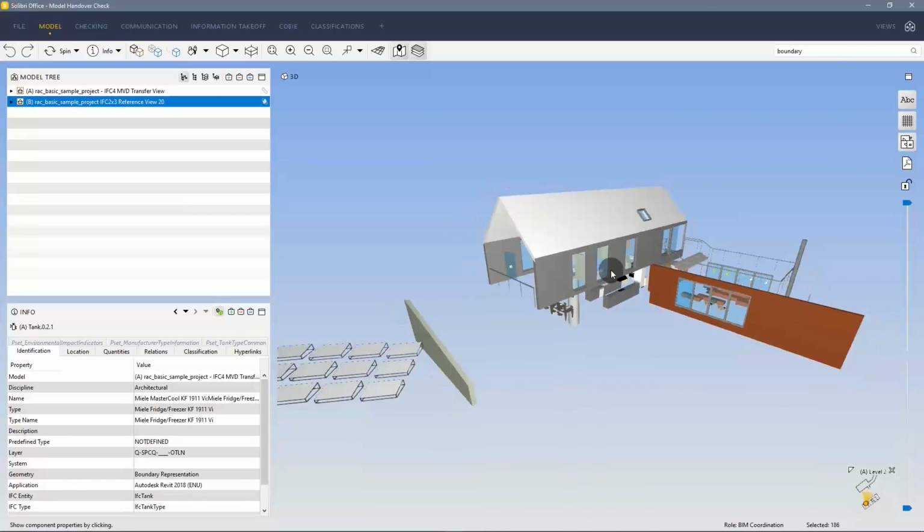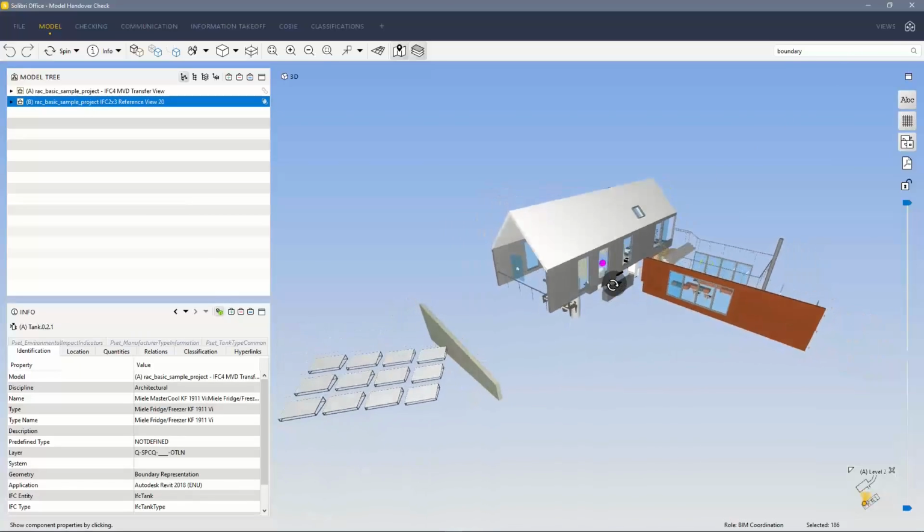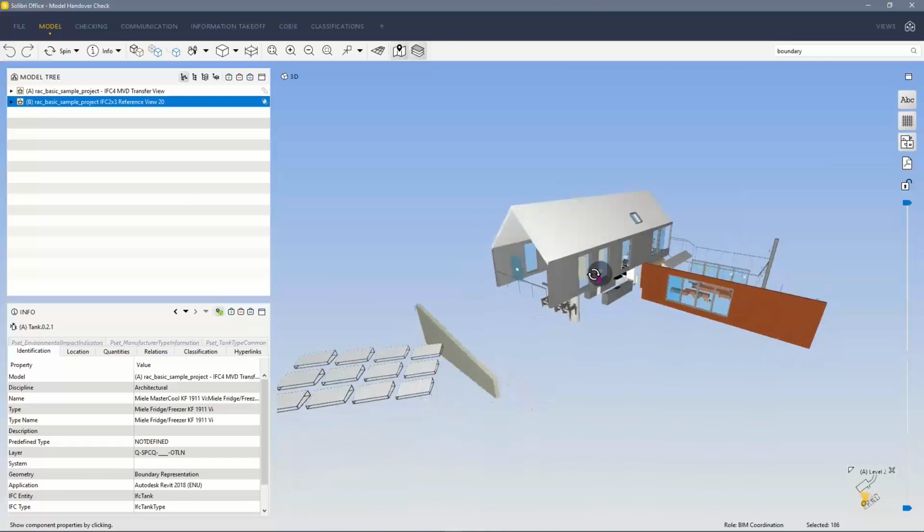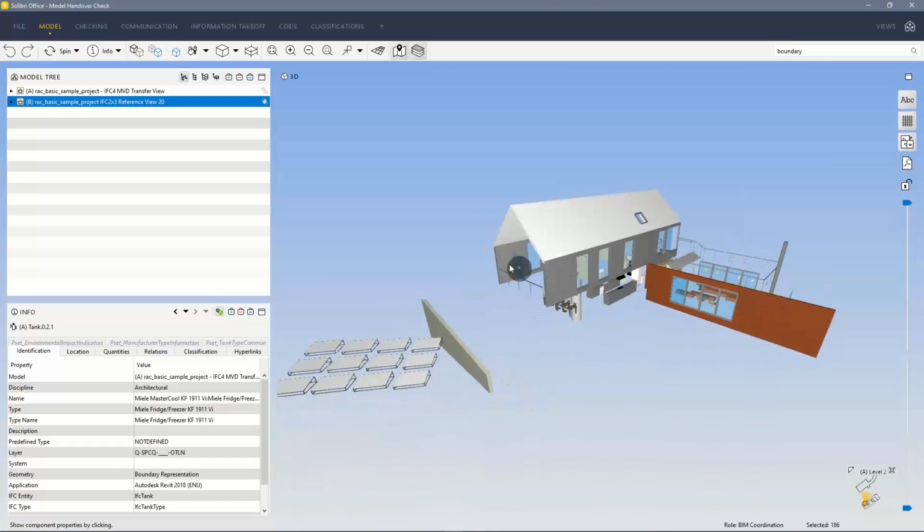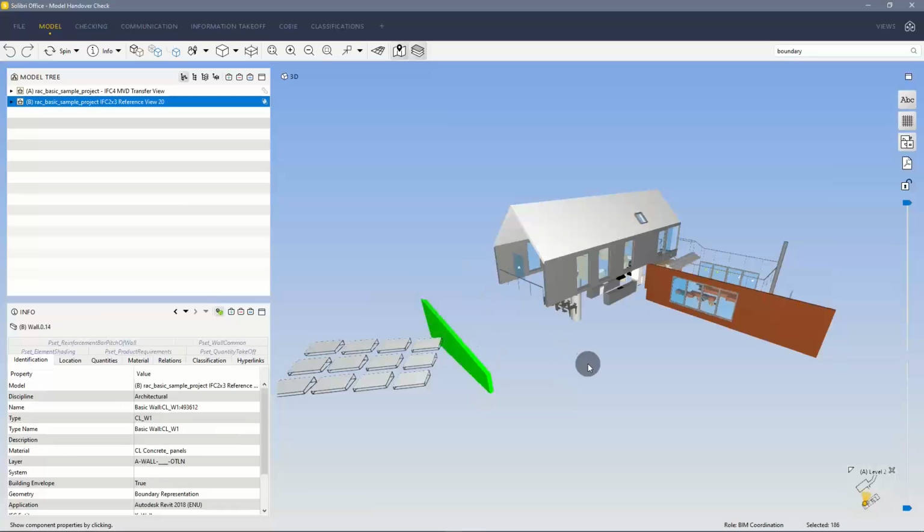Like so. Now, I'm interested in those elements because I know that, for instance, some elements in here, like that wall, those two walls, this wall here on the side, should have been built with implicit geometry, meaning some sort of extrusion or a profile and then an extrusion along the side. Now, that didn't happen in the transition from Revit to IFC. So there's no fault in Archicad.